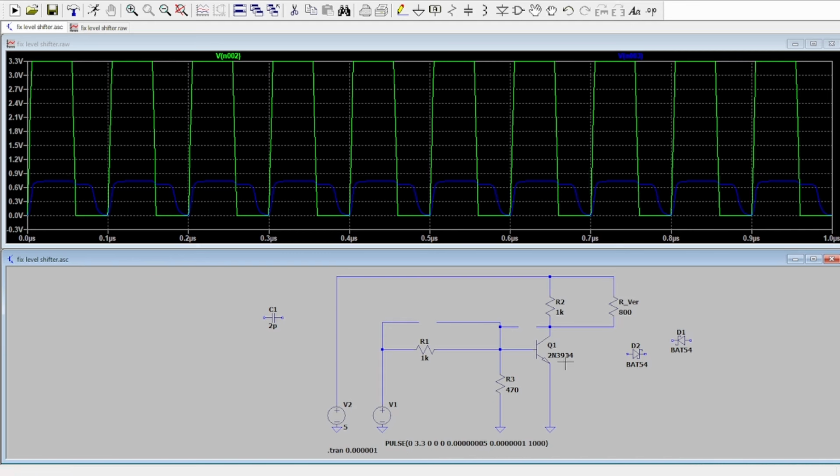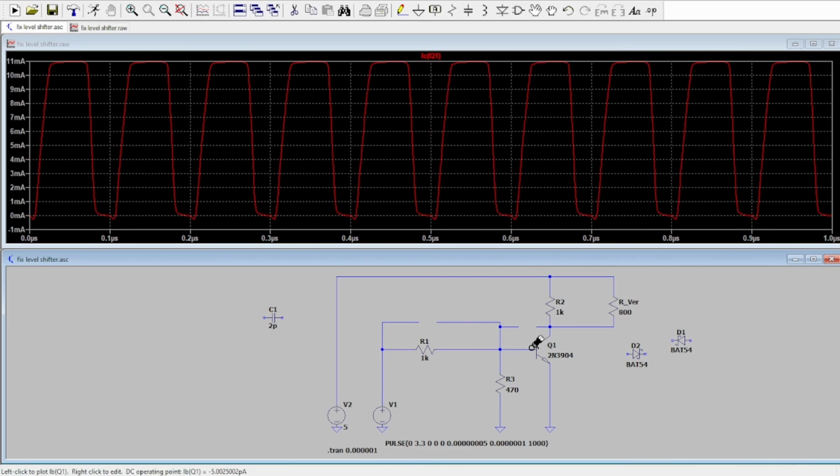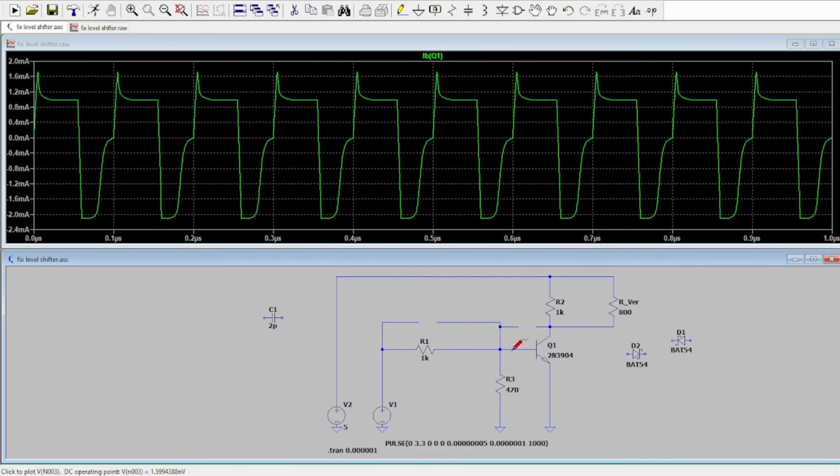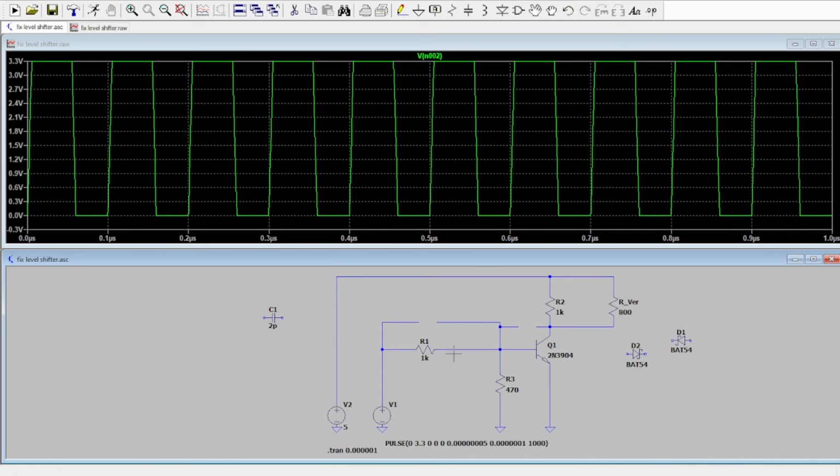And this is a point where I still don't understand what's going on, because apparently there's still some current after turning it off that flows through the collector to the base and then through this resistor to ground, which then slowly decreases until 0 volts. And then at some time, the input becomes high again, 3.3 volts again, and this complete cycle continues.